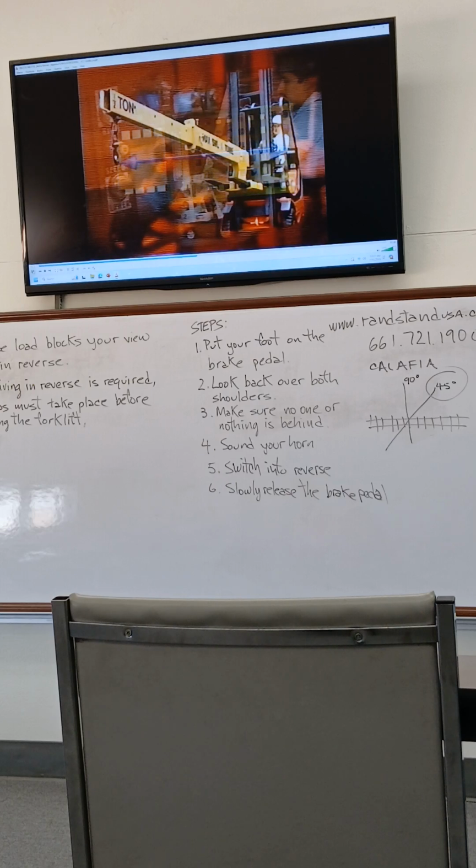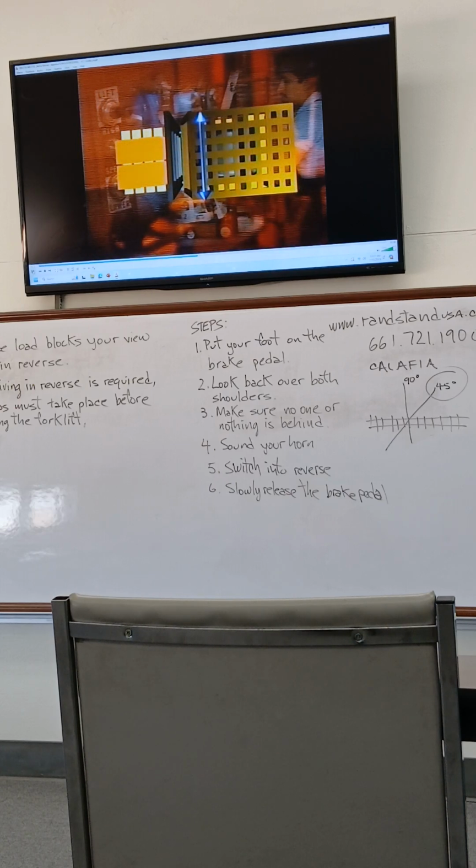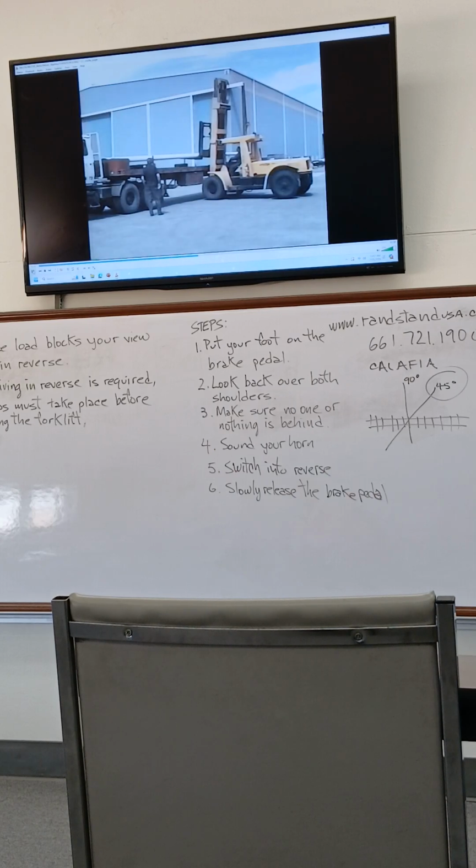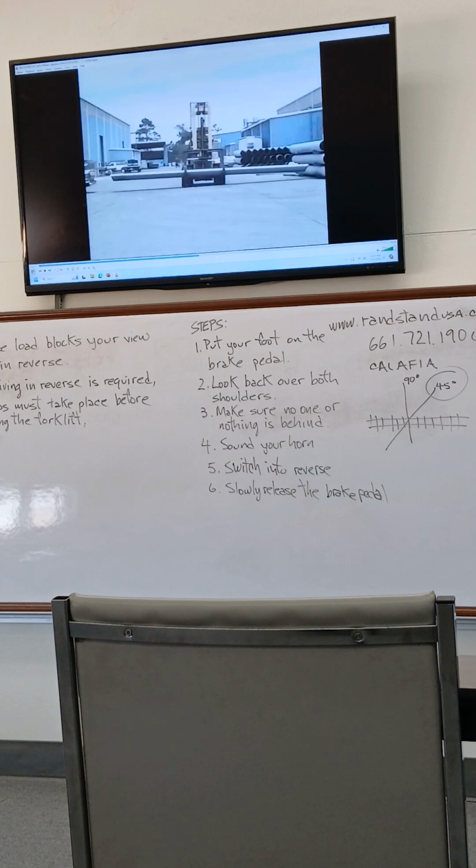This is demonstrated when you use boom attachments. Lateral stability is the truck's resistance to overturning sideways, as when using pipe attachments or extremely wide loads. Each class and size of equipment has different longitudinal and lateral stability principles, so it's up to you to remember how these affect your operation.